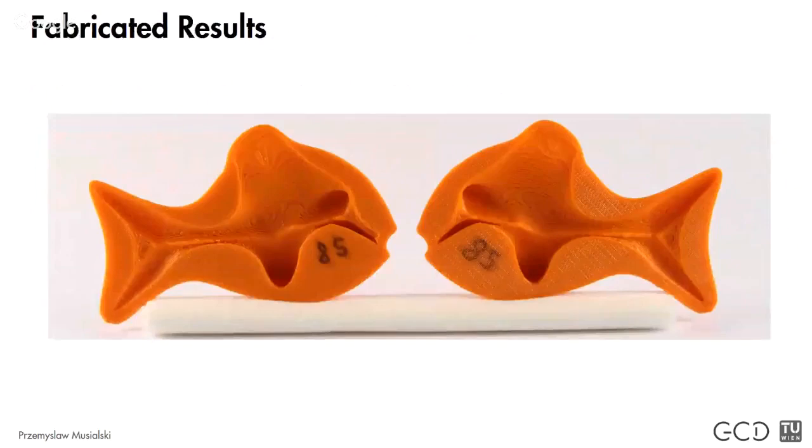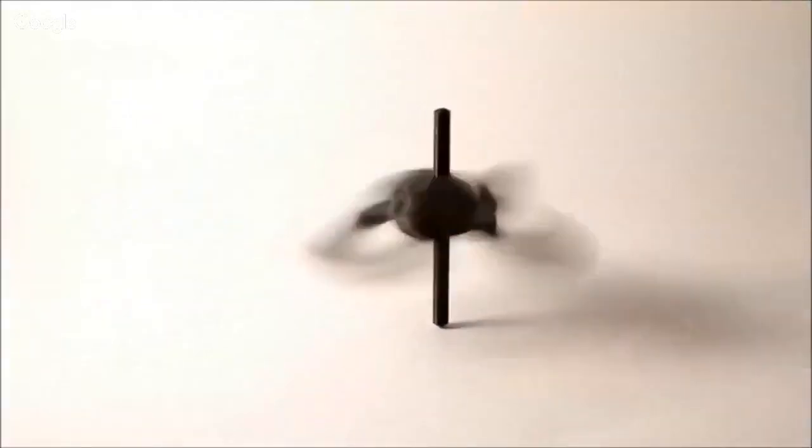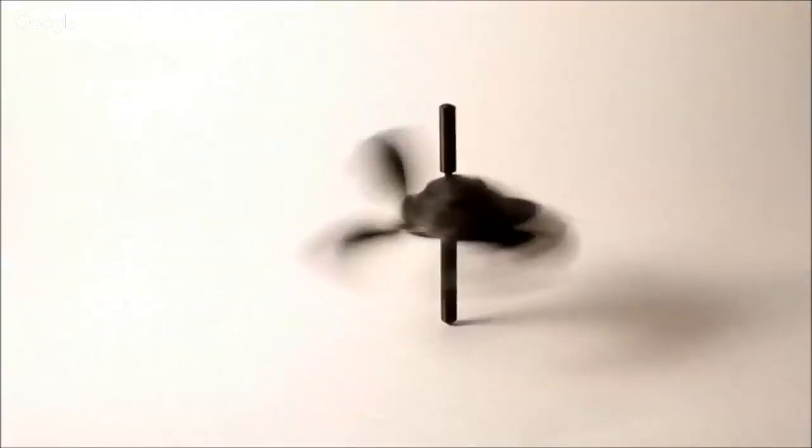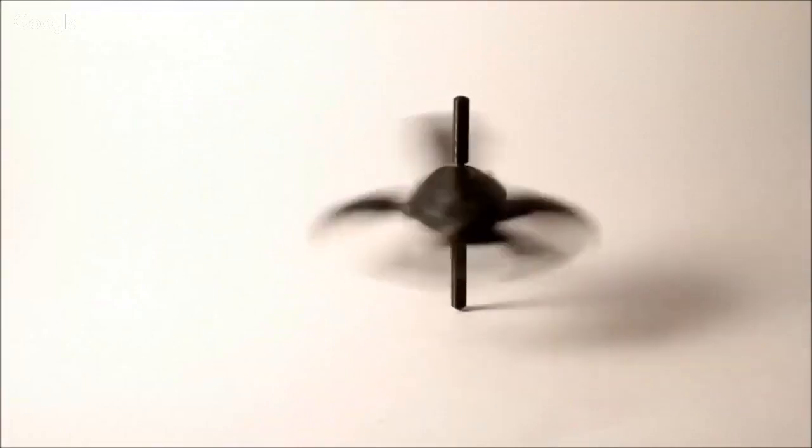So using this method, we have optimized mass properties. Mass properties describe the mass distribution within the object, which can in fact be computed as a function of the surface only using the Gaussian divergence theorem. So we don't have to discretize the whole structure in this case. We just use these two surfaces. Using this, here we have optimized the axis of rotation for this turtle.